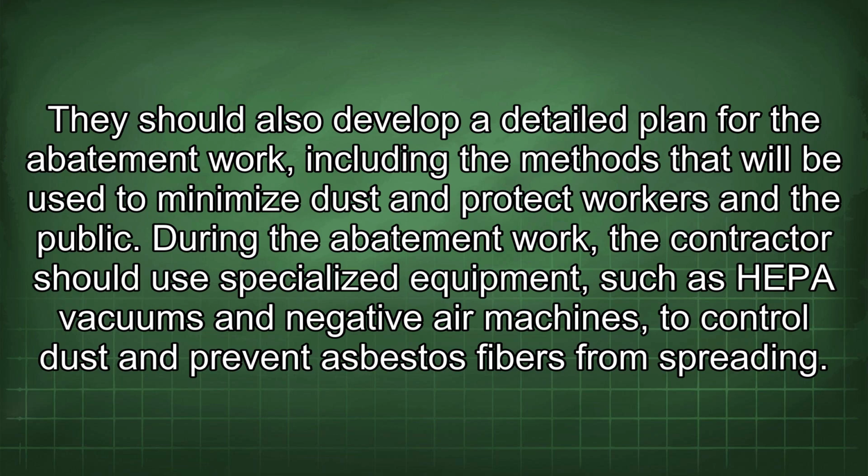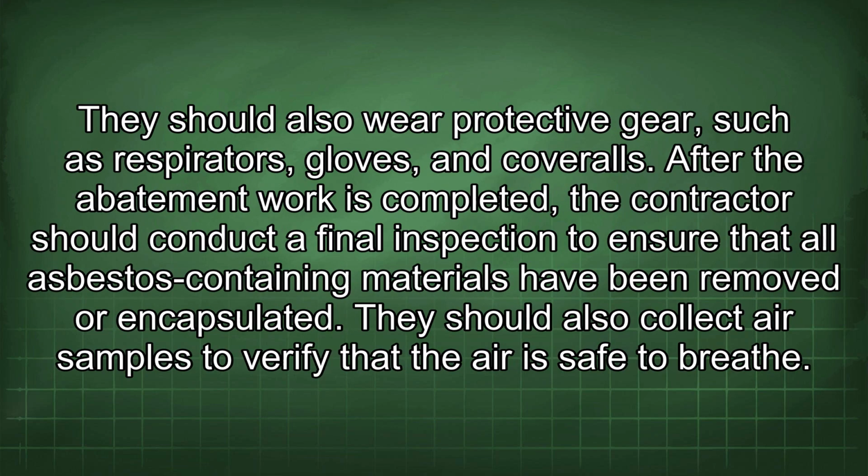During the abatement work, the contractor should use specialized equipment such as HEPA vacuums and negative air machines to control dust and prevent asbestos fibers from spreading. They should also wear protective gear such as respirators, gloves, and coveralls.